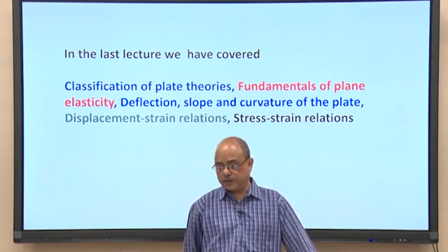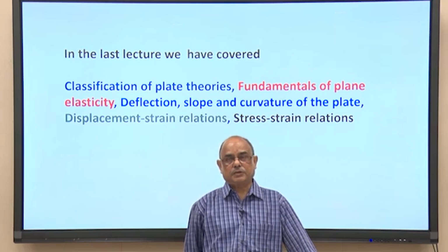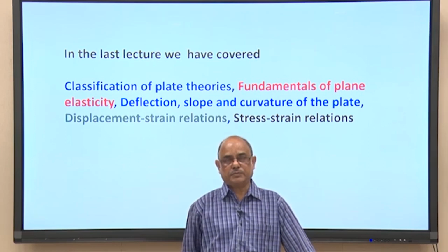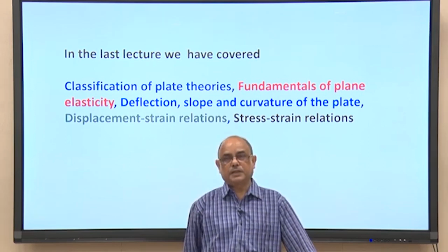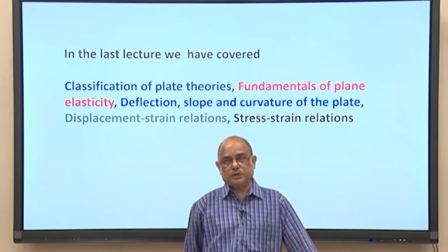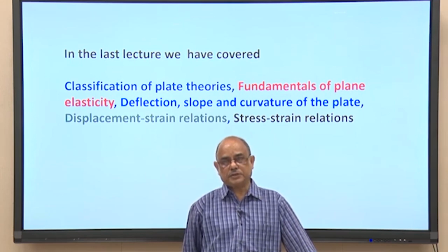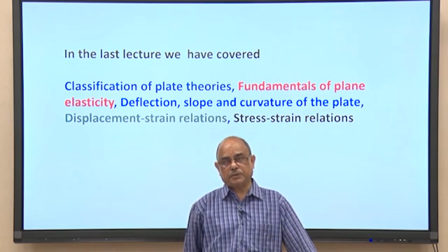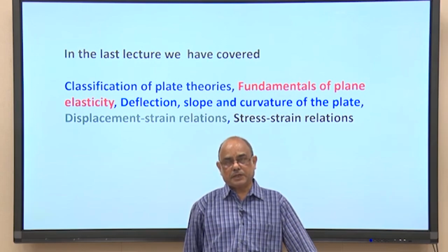Then we discussed the fundamentals of plane elasticity: how the stresses are denoted, 2 subscripts are used, what their significance is, what shear stress and normal stress are, and the concept of principal planes. Then in a plate, I discussed the deflection and slope, how the slope is measured in 2 directions, the interrelation between the slopes in any 2 mutually perpendicular directions, and the criteria by which the directions of maximum slope and minimum slope can be related.